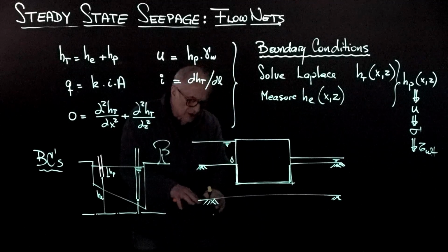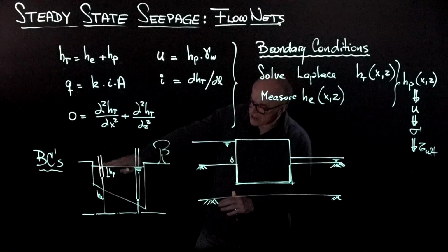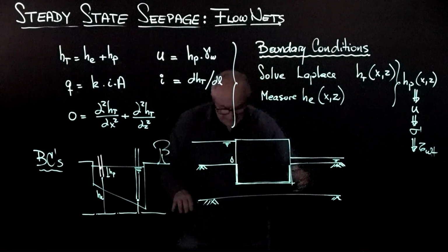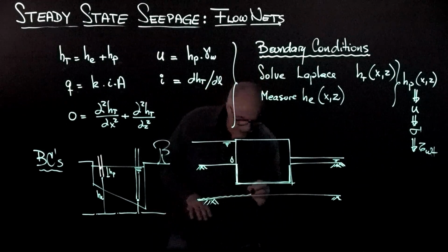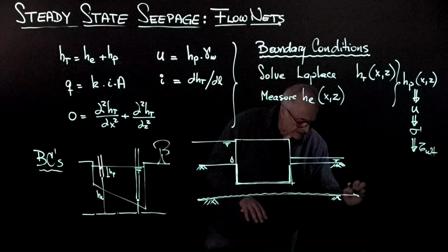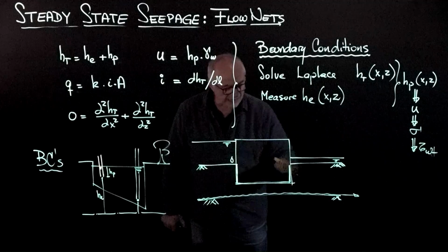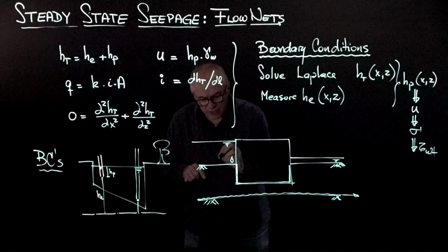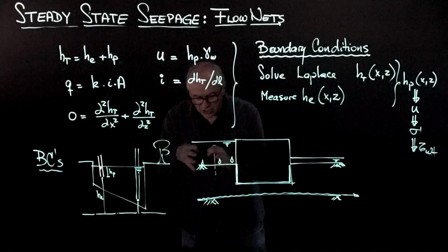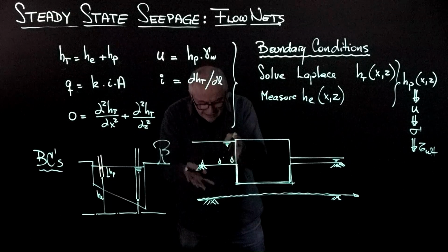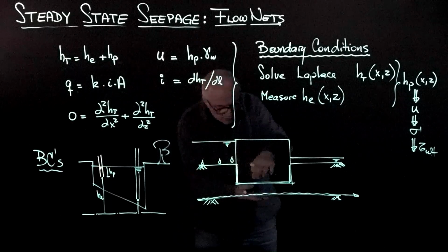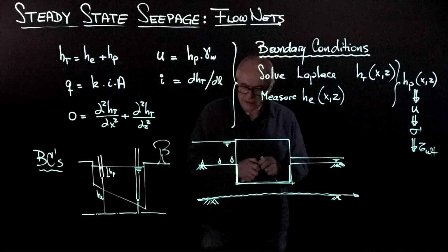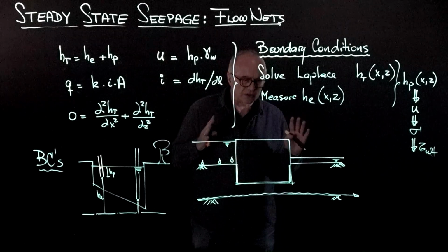And the longest flow line will start far away at infinity, will come along this interface, and will end all the way at infinity. So this is the longest flow line. For lack of colors, I consider this wavy line as the longest flow line. And all the flow, it doesn't matter where the water droplet enters the soil, all the flow will get constrained between these two boundaries, between the shortest flow line and the longest flow line. So these are two boundary conditions, the flow boundary conditions.